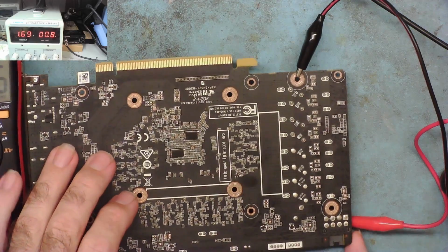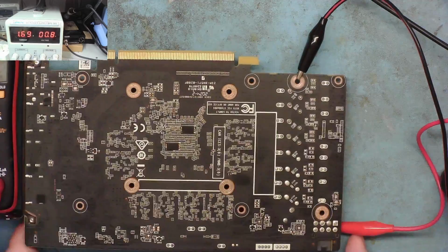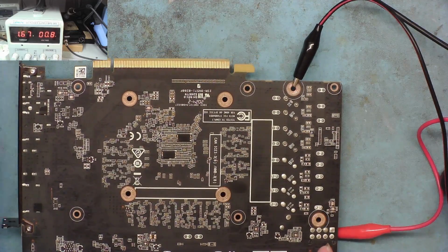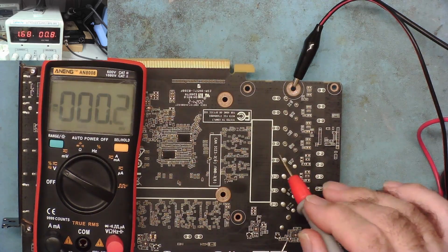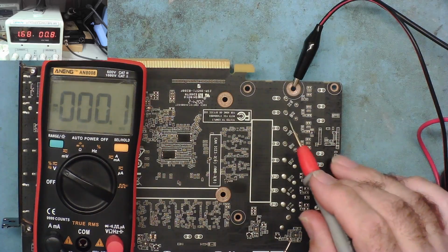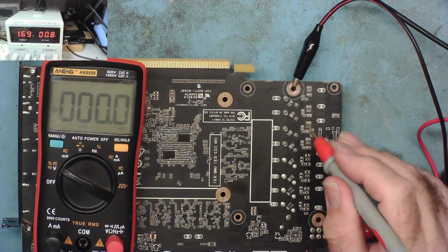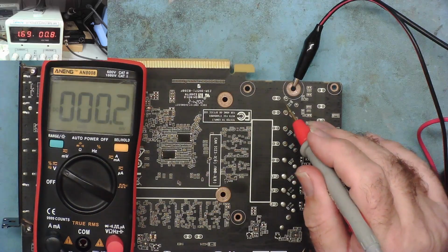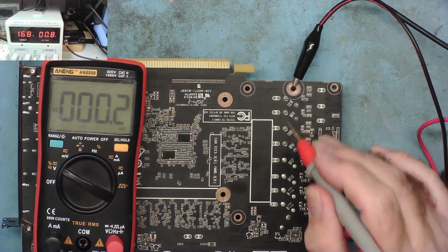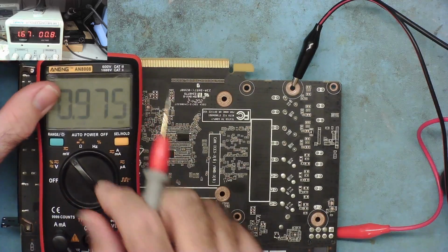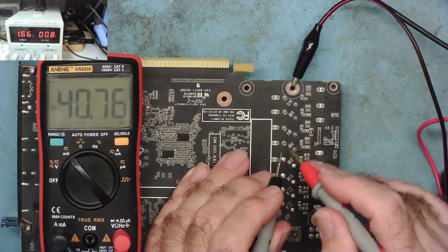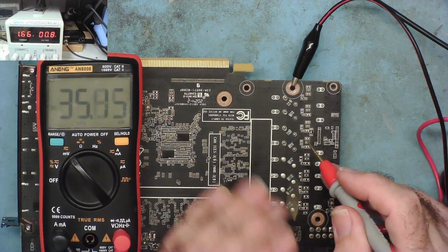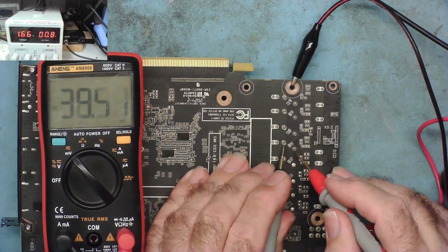This is a slightly different variation on the method I just used. In this case, we're injecting current again into the short from the 12 volts. And what we're going to do now is try to determine which of these coils the current is flowing through. The idea being that the one which has the short, which is passing current through the coil, will read a voltage across it. So we can go to the millivolts range on here and have a look. If there's no current flowing through the coil, and the coil has some resistance, albeit very low, we shouldn't see any voltage drop across it.